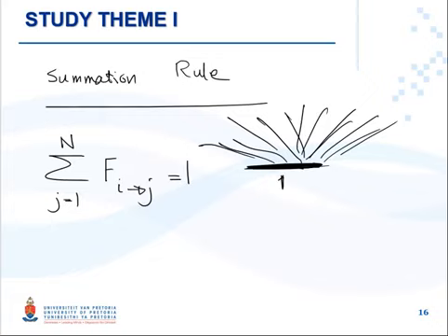I don't care how many surfaces are around, but those surfaces will get all the radiation that goes out of surface 1. So basically, what fraction of the radiation leaving surface 1 strikes the surfaces I just mentioned? All of it. So 100%.